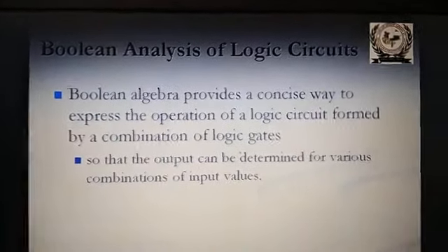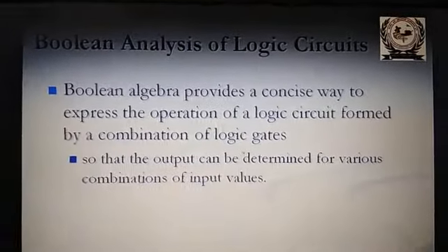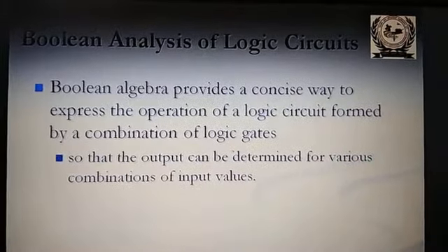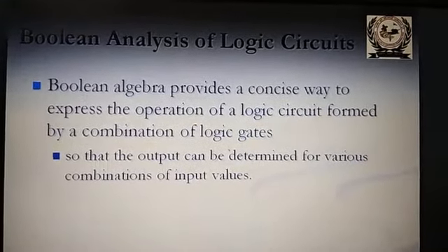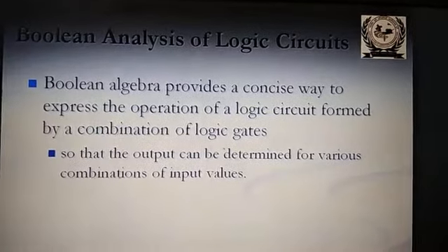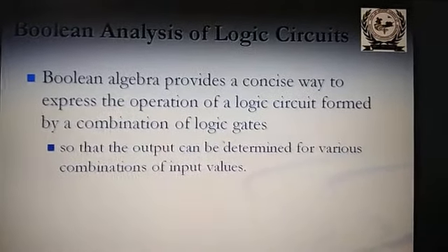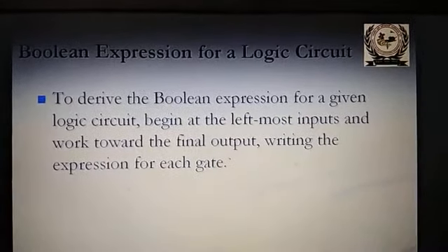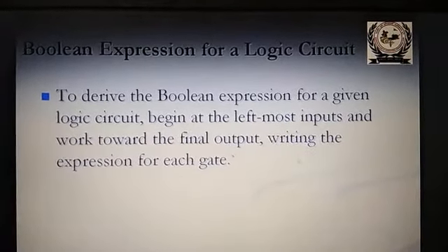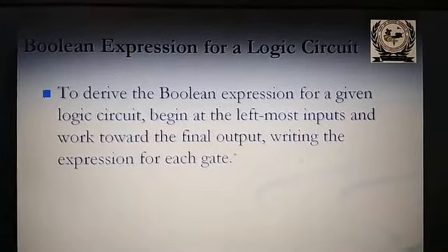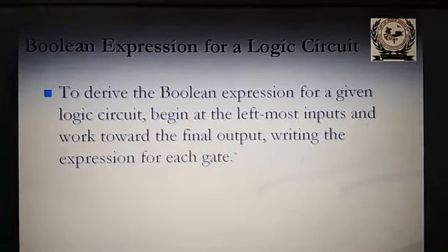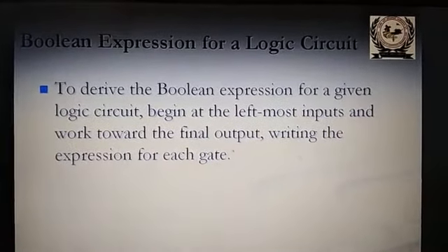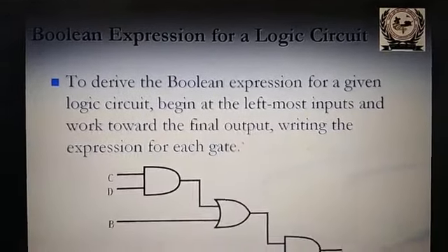Then Boolean analysis of logic circuits. Boolean algebra provides a concise way to express the operation of logic circuits formed by a combination of logic gates, so that the output can be determined for various combinations of the input values. Boolean expression for a logic circuit: to derive the Boolean expression for a given logic circuit, begin at the leftmost inputs and work forward to the final output, that is from left to right, writing the expression for each gate.